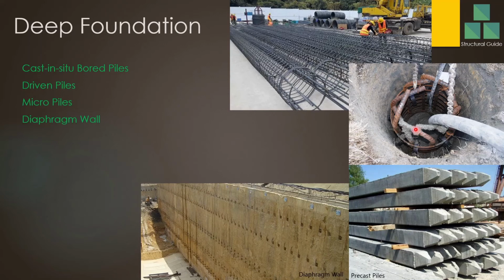In addition, steel piles are now also constructed in this manner. A steel casing filled with concrete will be cast as a micropile. If the steel casing capacity is not adequate, we may put a reinforcement cage inside the steel casing to enhance its strength. Those types of micropiles are also there.